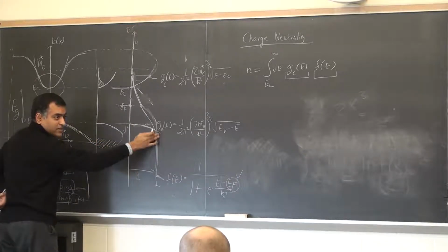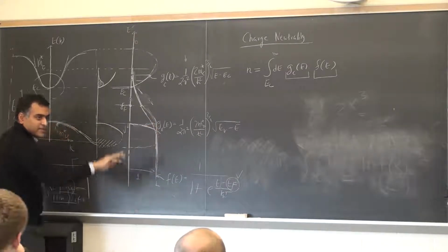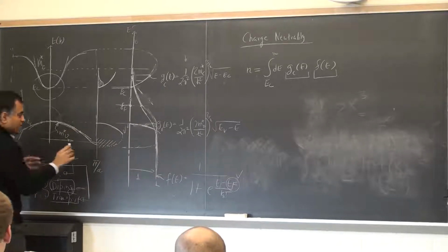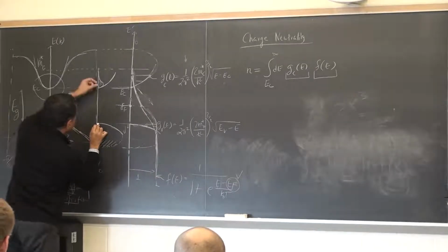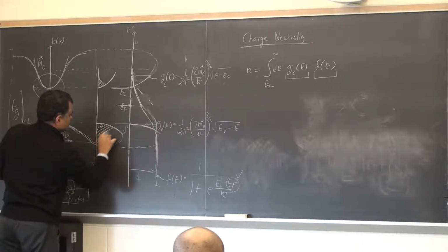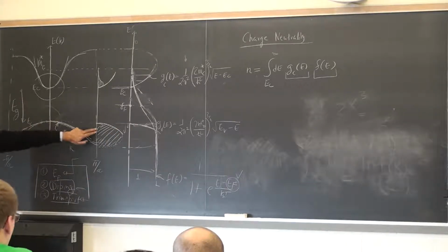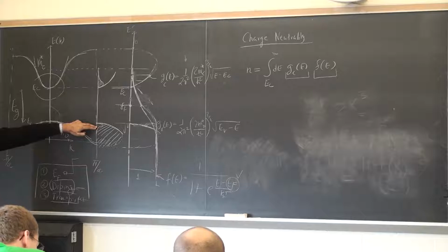You see that? This Fermi function is 1. But as you go up, there's a little tail that drops here, right? So those states are empty. So here also you have a mirror reflection, sort of, not exactly, but something very similar, except those are empty states. Does that make sense? Those states are depleted of electrons. Then those are the holes. You don't have those states there, right?